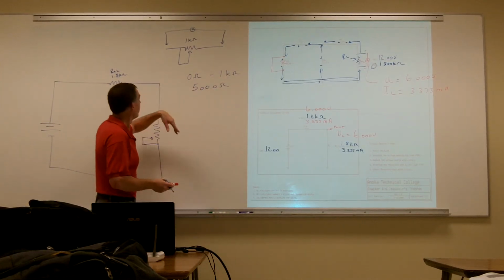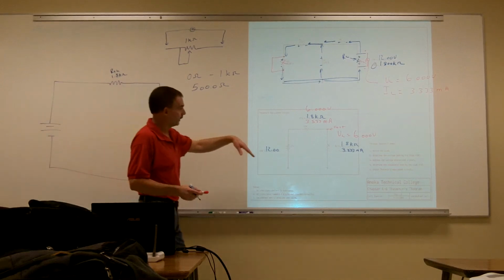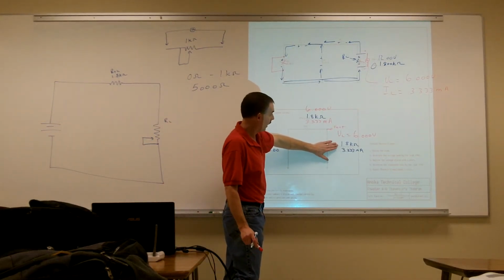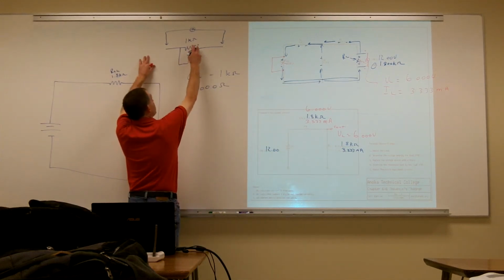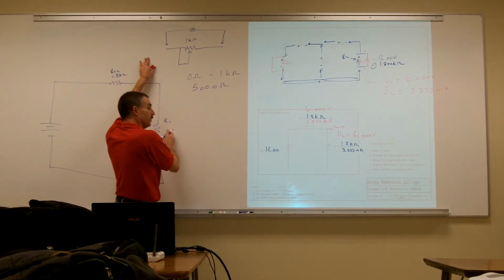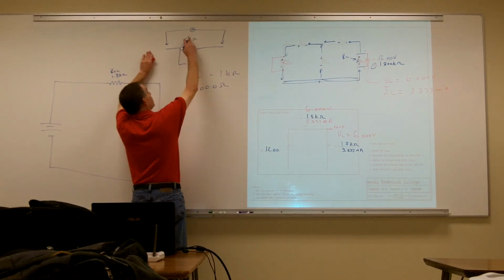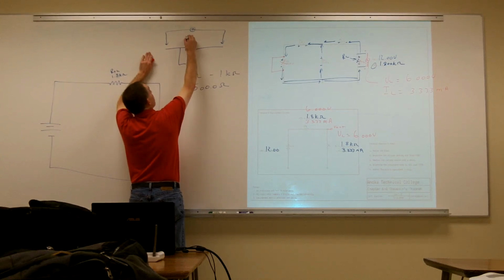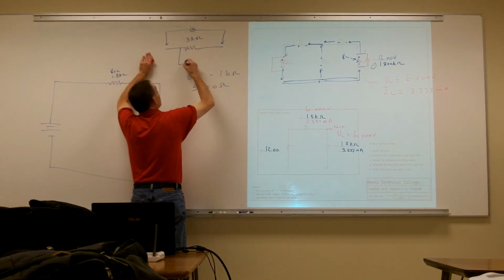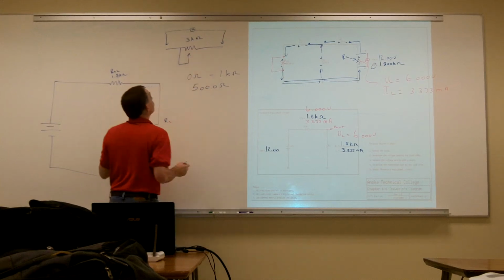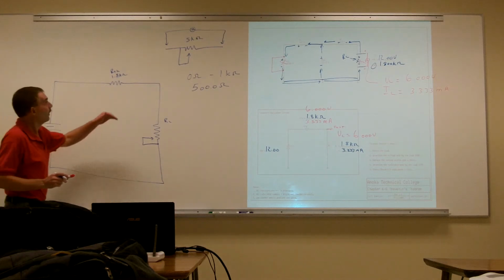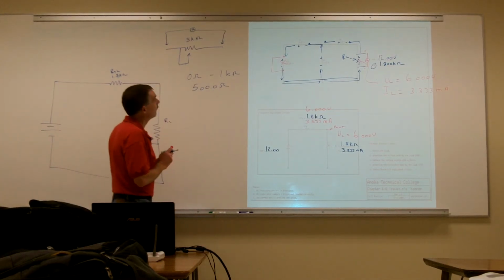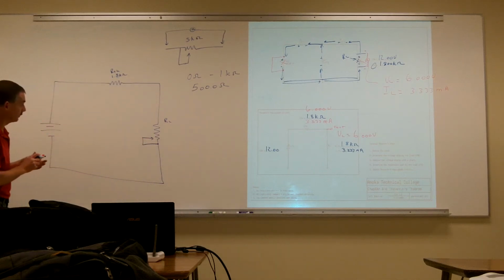ohm. So, for example, if we wanted to verify what's going on with the circuit, I need a resistor that's larger than my 1.8 kilo ohm. The next available one in our parts kit is probably our 5 kilo ohm. So we can take our 5 kilo ohm potentiometer, wire it up as a rheostat, and now we have an adjustable resistor. We can tune that resistor to be exactly the resistance that we want.